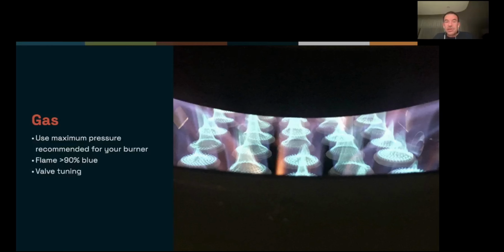But what they usually don't tell you, and what's important to understand, is that you won't have the full productivity potential of your machine. So if you have 30 instead of 50, you'll have roughly 60% of the productive capacity that you would have at 50. So if you were to roast full batches, you might have to roast them a lot slower, or you might have to roast, let's say, 60% batch size to get to the same roast time as you would with a full batch if you had a higher gas pressure. So please keep that in mind.